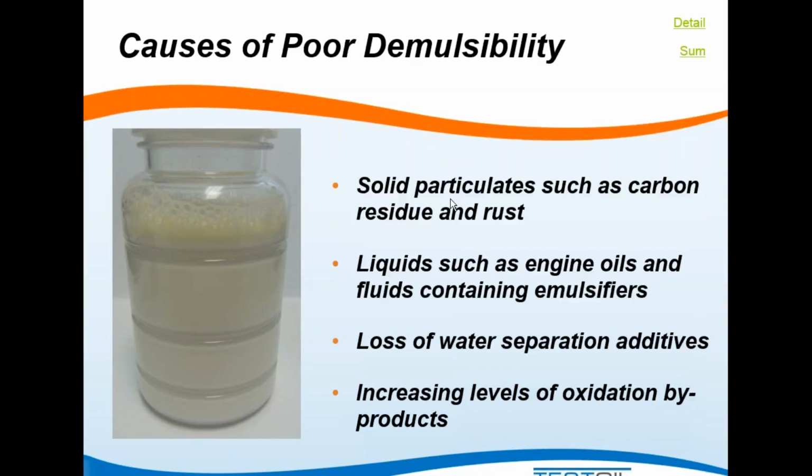Things I have seen in the past: I have seen sometimes customers send samples in with different mixtures of oils and having success that way. But I feel like that's hit and miss. It really depends on what the root cause of the failing demulsibility is. And I've seen where different mixtures of oils, even at the same ratio, one may pass, one may fail when you try to mix things up like that. So if you want to really fix it, I would say change out the oil.